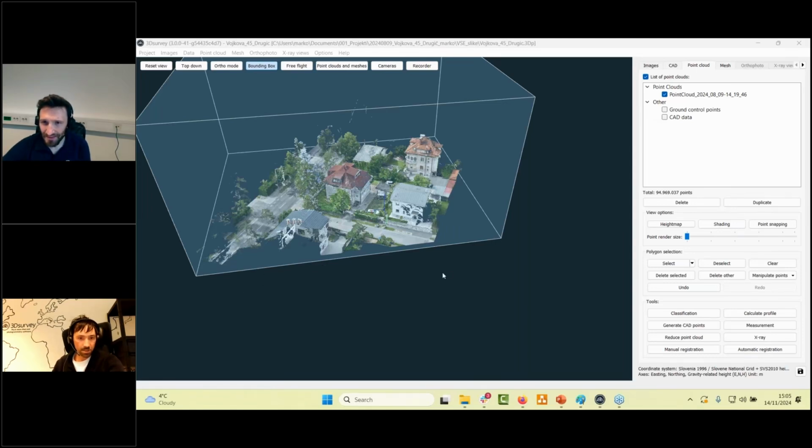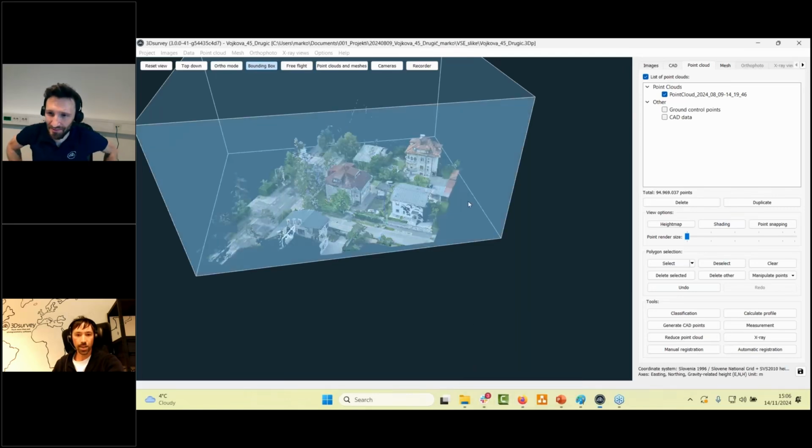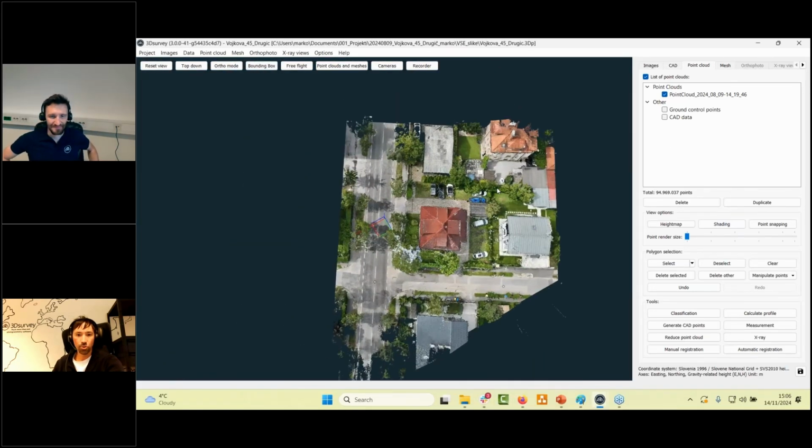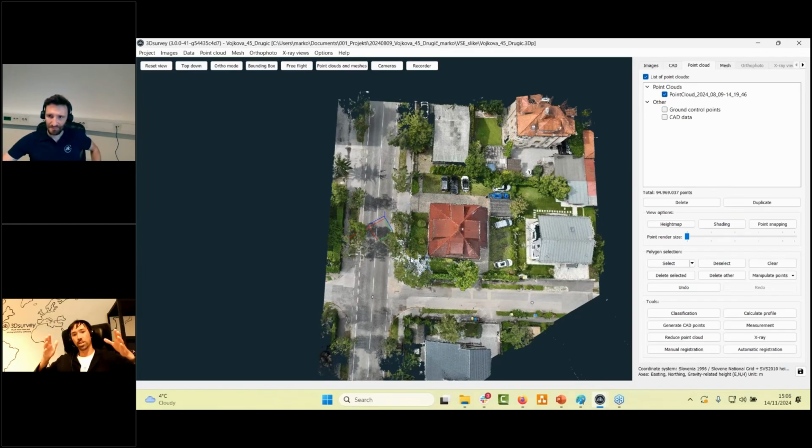Okay, then there's a question from Bastian. What do you mean by true orthophoto and standard orthophoto? Probably true and traditional is okay. So, super quickly: with the true orthophoto, you get the roofs in the right locations. With the traditional orthophoto, buildings are always turned a bit to the side, because the traditional orthophoto you are doing with the ground terrain model, so digital ground model. With the true orthophoto, you are doing it with the full 3D mesh, so all the buildings are inside, and then the projection of the image goes to the exact height, to the exact mesh, and with this you will get the nice roof positions also.